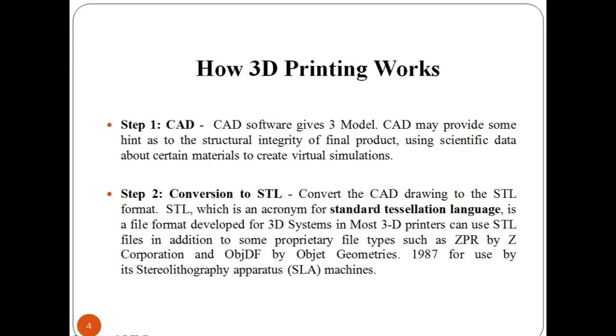Have a look at the process to create a build file. In Catalyst or Insight, open your CAD file that is in STL format and select a material, color and slice thickness. Pick a build and support style to match your application requirement.